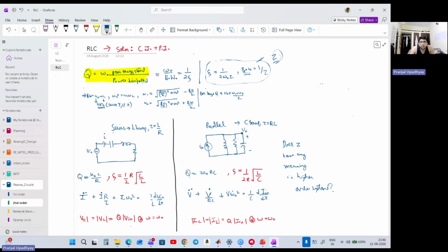Again, since we know that this is a series RLC circuit, were we to sketch the impedance of the circuit, it will look something like this, right? Where this maxima will occur, when will this maxima occur? By the way, is this impedance or admittance? This is admittance actually, because admittance will maximize for a series circuit at resonance because the imaginary components cancel out. Alternatively, the current will maximize. So we can also say that this is the expression for the current, right?